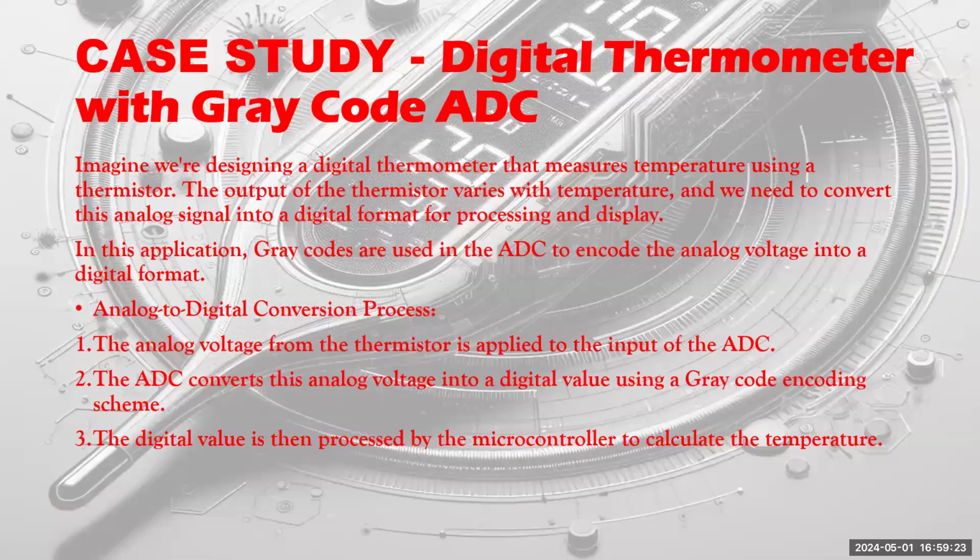That's a good example. Only thing we have to remember is that the example she has picked is a slow transitioning data environment. You are unlikely to encounter sharp temperature transitions. It will be progressive. So the sampling period will be so fast that you will only capture at a maximum one transition of the thermistor value being translated into some kind of digital number change. So this application is ideal because the transition is not so quick that you will jump many codes. Likely you will be changing from a given gray code to its next gray code for subsequent readings. So that's why it is applicable there.